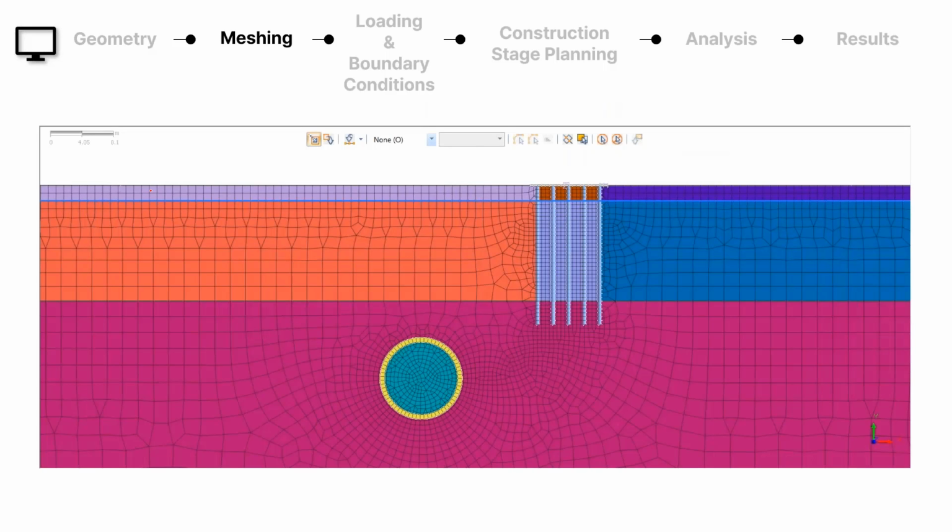So we follow the hybrid mesh in here. The hybrid mesh kind of looks like this. You have quad elements in here. And you can see in the transition zones, we have triangular elements. So triangular elements provide the transition from a smaller quad element to a bigger quad element, to ensure that the uniformity of the mesh remains the same throughout the model. That is why both kinds of elements are necessary.